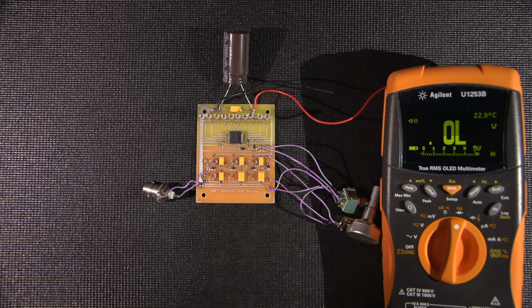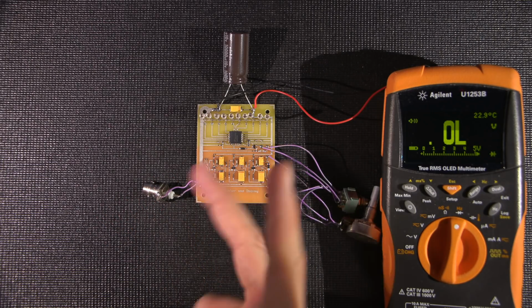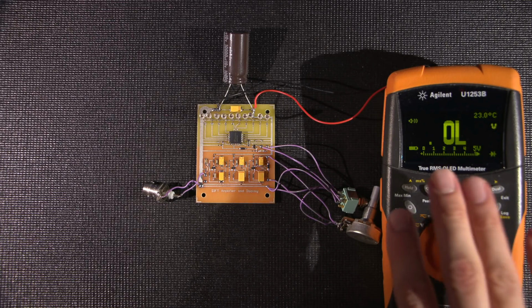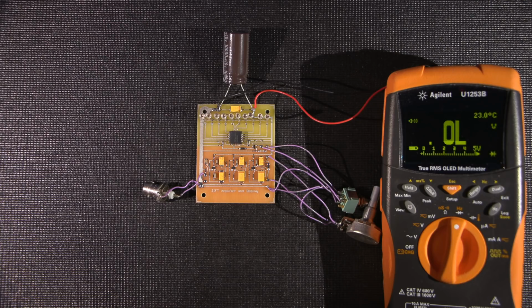Now you can select or move around the emitter and collector in this test. What I'll do is I'll also post that video on how to use a standard diode checker to test these transistors just below this video. It's a really, really simple thing to do, and you can just buzz through circuits really quick. Basically, it's a go or no-go test for transistors. So this should check like two diodes.